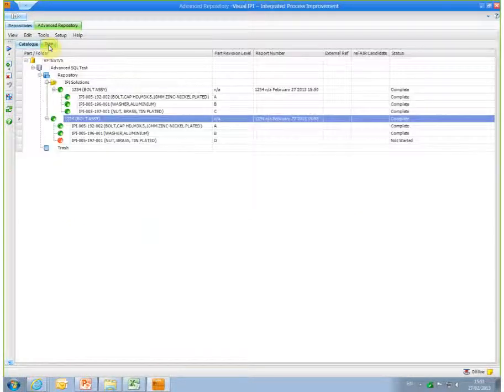So again, this is a very new and recent development. GE in Bishop's Cleeve, Cheltenham are actually running with it, but that is just a flavour now for a more advanced repository, a key tool in identifying revision changes to parts that exist in an assembly and whether there is a need for a first article inspection report based on the detail part. If the detail part within it has changed, it will flag up at the top level assembly a potential candidate for doing that first article inspection report.